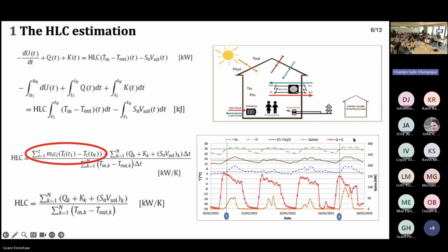The ventilation and infiltration might make variations in this heat loss coefficient, but look at this. What is the uncertainty of this guy here? Actually, here, if you calculate it and if you would be able to measure all this, the uncertainty will tend to 0. But the thing is that many of these things are not measurable. And this is very important. This is a physical model. If I would measure this perfectly, I will get the perfect measurements.